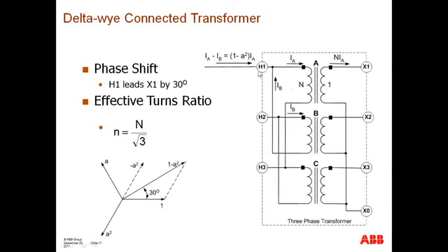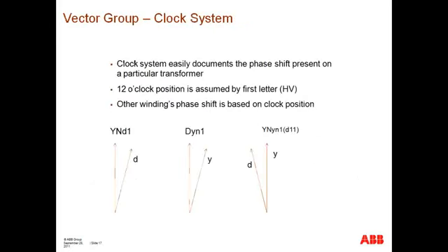So, for a particular distribution substation, you have a 138 to 13.8 kV transformer, 13.8 kV being a distribution level voltage, and this particular transformer will provide that transformation from a higher voltage to a lower voltage. The Y connection is on the distribution side, so there's a healthy source of zero sequence currents, so that phase-to-ground faults, or faults involving ground, can be easily detected within that particular network. And this is a very, very common arrangement, utilized here in the United States for our distribution systems.